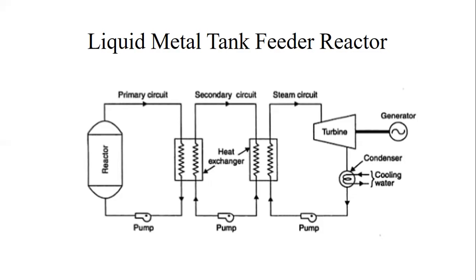The high concentration of fissile fuel and the absence of moderator makes the core of the fast reactor smaller than a thermal reactor of the same power. With a high power density, thin fuel pins are used to minimize the temperature drop through the fuel. A coolant with excellent heat transfer properties is required to minimize the temperature drop from the fuel surface to the coolant, and it must also be non-moderating. This rules out water, and the best coolants for fast reactors are liquid metals such as sodium.